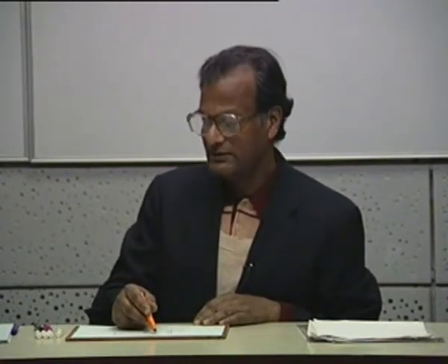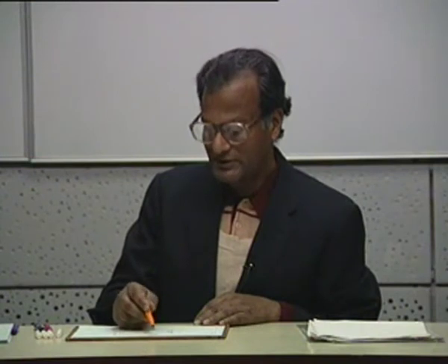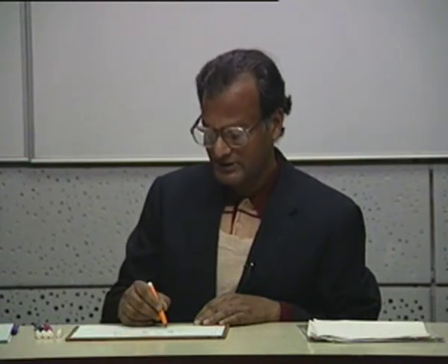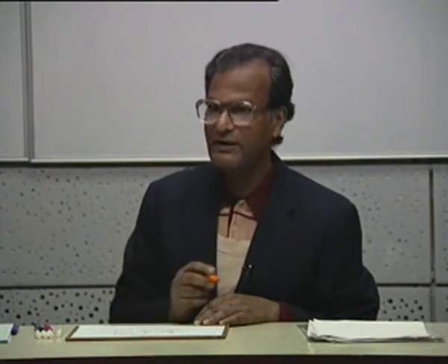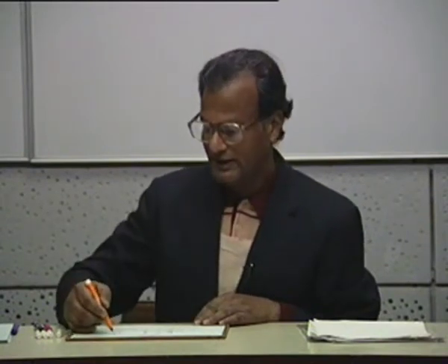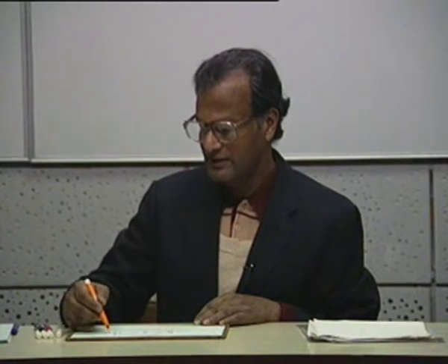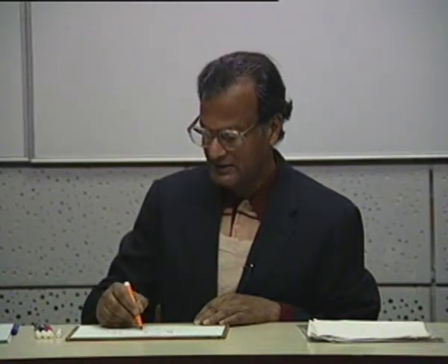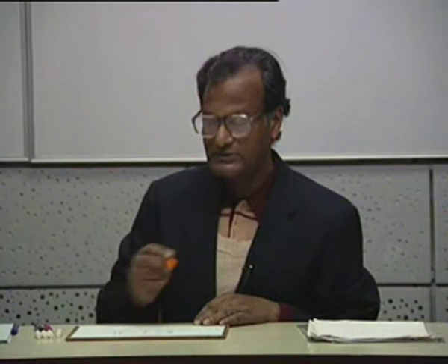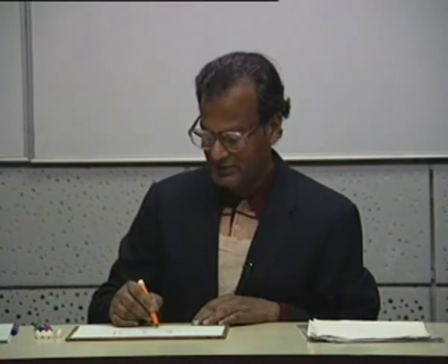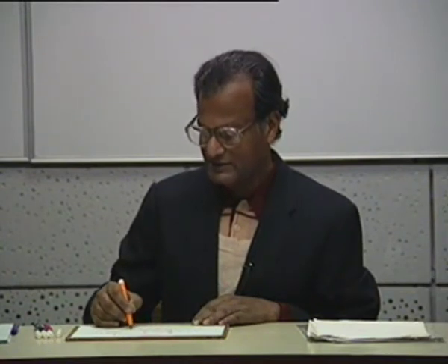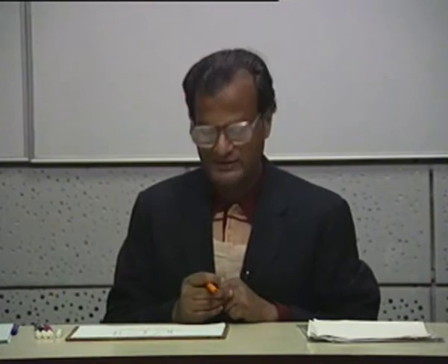Whereas V1, this voltage drop, goes from plus to minus, so it shall be considered negative, V minus V1. Then when I come to the third element here, the third resistance, from minus to plus, this shall be considered positive, and this sum shall be equal to 0, which can also be written as capital V equals V1 minus V2, or any other way that you like.